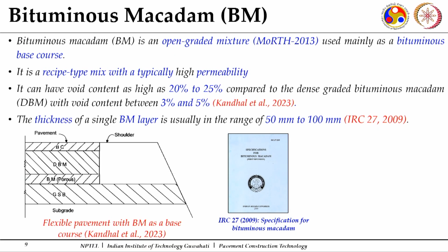So, knowing the gradation helps us make combinations of mixes having different distributions of aggregates within them. We can have a dense graded one, a gap graded one, and an open graded one. So, let us go through the different kinds of mixes. As I mentioned, for low traffic, less than 20 MSA, bituminous macadam is referred for use as a base course mix. What is that particular mix?